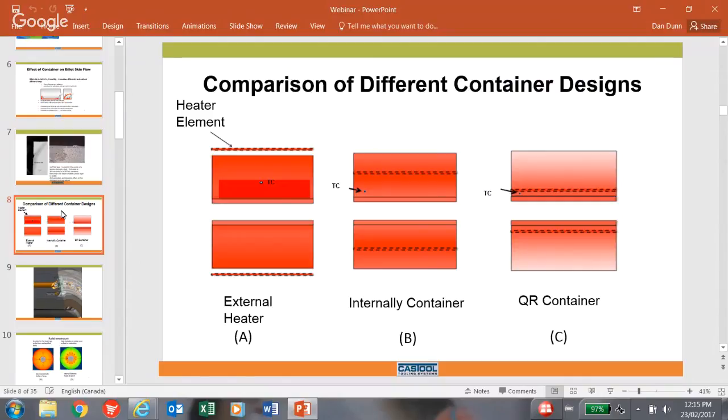In figure C, we see the container QR method. This method has the thermocouple strategically placed in 4 areas of the container, very near to the liner. The element location close to the liner is strategic, as the goal is to manage liner temperature and not container body temperature. By moving the elements close to the liner and the elements close to the liner in proximity of each other, accurate and quick response to changing temperatures in the process are achieved.